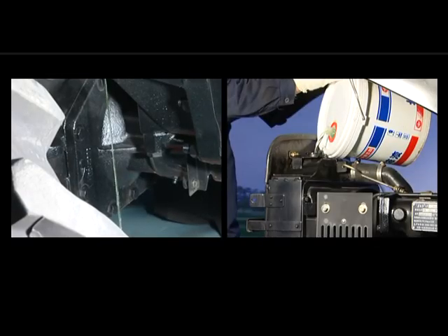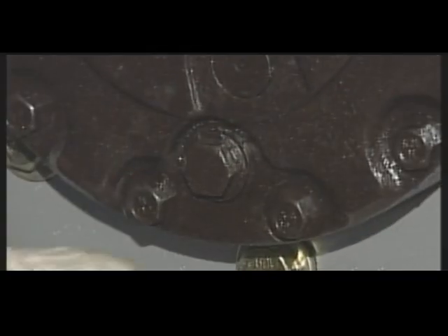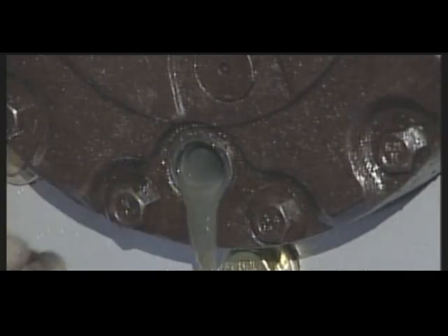1600 hours technical maintenance: full contents of completing 800 hours technical maintenance. Change the antifreeze of the water tank. Turn the wheel hub when changing front drive axle oil. Keep the oil drain plug at the bottom, unscrew the plug, and drain the contaminated oil.